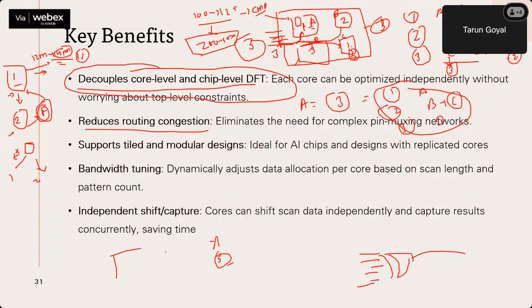Earlier, when we were designing the EDTs, so this was the 4 EDTs, right? We were placing a channel mux. So this is my channel mux, which gives this input to this EDT, this input, and then this, and vice versa. Also taking a scan out, and then we are taking them out. So this was creating a lot of crisscross also. We call it star connections, star based EDT implementations. Now it's a bus.